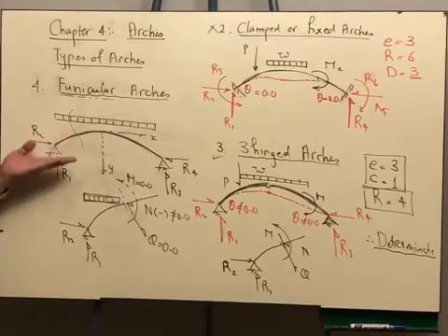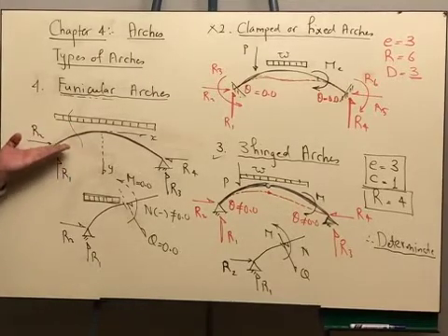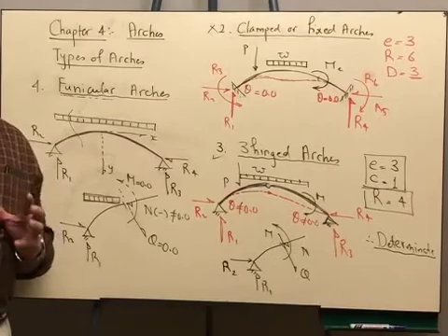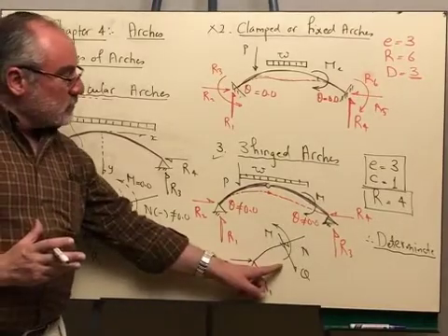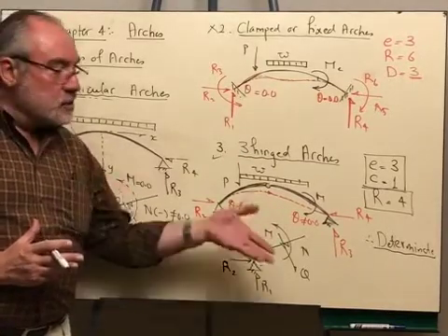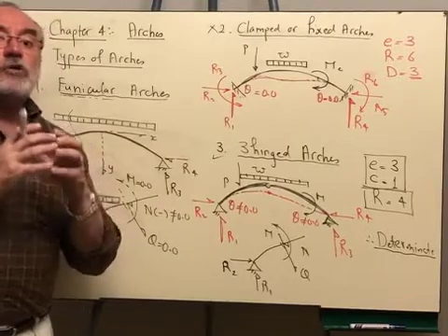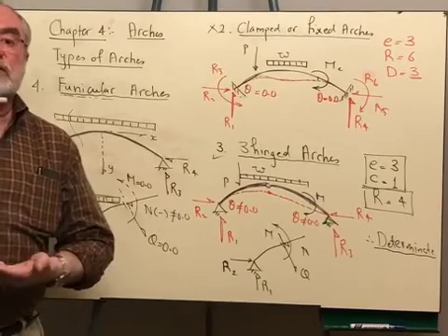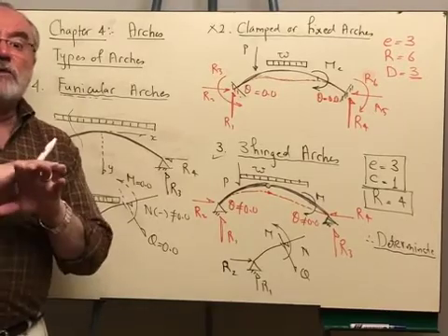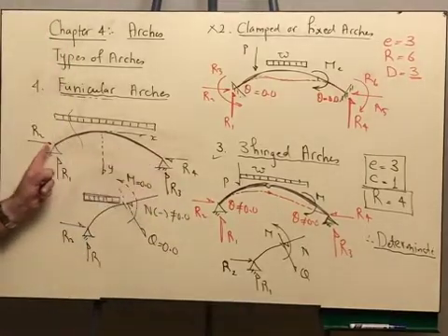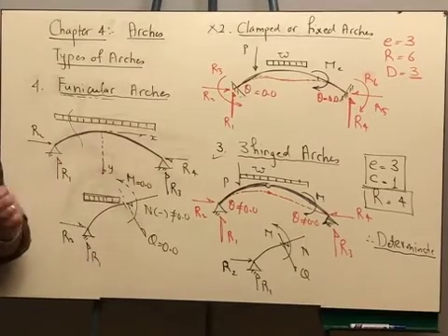So this is the cheapest type of arches because you know that the bending moment is having the most severe effect on any cross section. When you are having internal bending moment in the clamped or in the three hinged arches, in the general three hinged arches, you will have to design the cross section to afford or to stand the effect of the bending moment. This will let the section to be very large. If you want to make the arch optimum, the cheapest solution, then you have to select the shape of the arch so that it would be a funicular arch. Our lecture today will be focused on funicular arches.